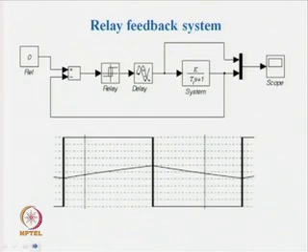Now, when the output waveform is zoomed here, we see that the output has a 0 crossing over here. So, let us start with time t = 0, and again we have a 0 crossing at time t = Pu/2, where Pu is the time period of the output signal. Now, at time t = theta, interestingly we get the peak output, which is designated by Ap. Ap stands for peak output of the system.